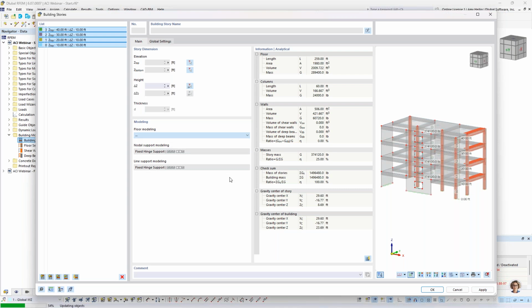going to define here a semi-rigid diaphragm. Now remember, for rigid or semi-rigid diaphragms, when we carry out that separate 2D calculation, we're replacing the walls and the columns underneath it with line and nodal supports.